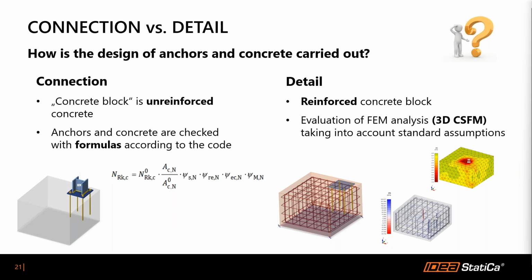On the other hand, in Detail application, where the 3D model type is implemented, the concrete block is modeled with 3D solid elements and is reinforced. In fact, it must be reinforced. This application is developed only for reinforced concrete. It utilizes the method called 3D CSFM, but more on that a little later.